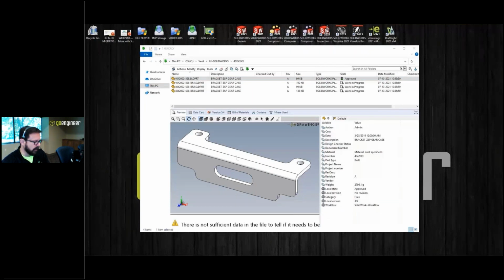Now, this was just a single piece part. I think people kind of wonder why the form for this, if they just try it on a single piece part, looks like the copy tree. Well, sometimes people are doing this on an assembly. They're taking a small subassembly and they're going to iterate. That could be swapping out parts or making physical changes. And so that's why that add prefix, add suffix is nice, because you can take a whole little subassembly, create a branch, and then the components you want to change can all be given the suffix of BR1, BR2, depending on how many branches you want, okay?